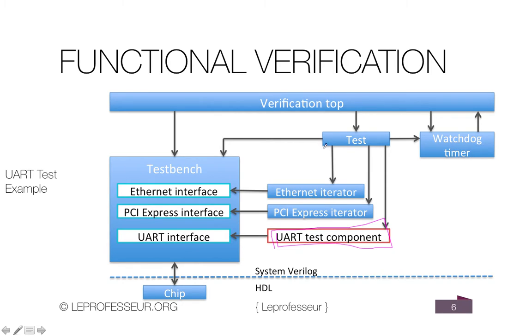And here you have your test. Okay, so the test is communicating with all these components, and you have here your watchdog timers for scoreboarding and timing purposes, and this completes your verification environment. Okay, now all those individual components, you can make use of an object-oriented programming approach, and you can develop these components in SystemVerilog in an easy way, and then connect all these pieces together and good to go. Not very difficult. Good.